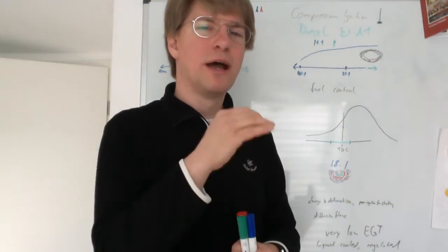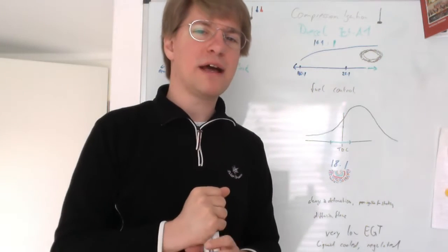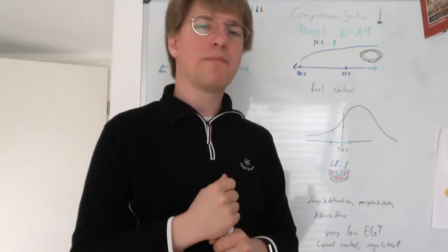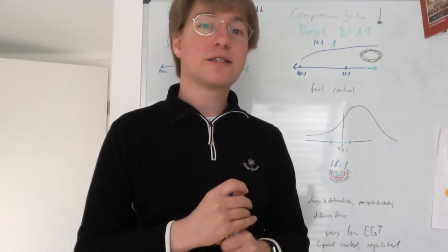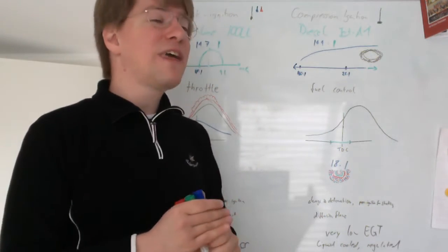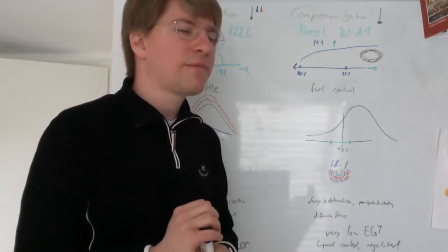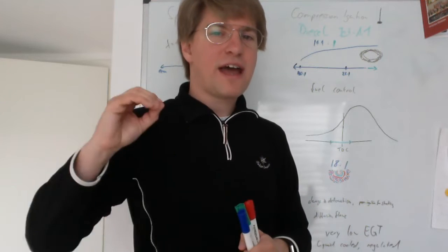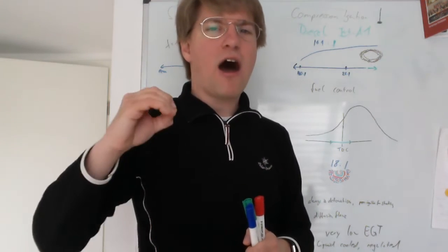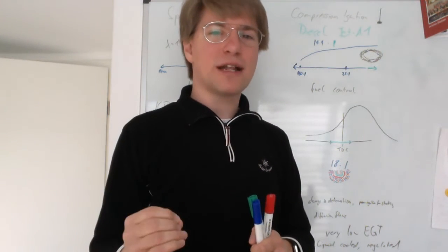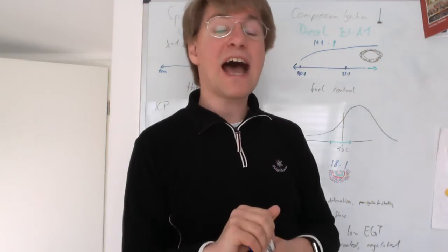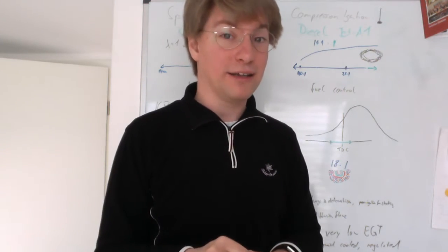Detonation happens when part of the fuel-air mixture ignites by pressure alone. So you can think of a diesel engine as an engine that constantly, always, and exclusively runs in heavy detonation. And that is why they sound so ugly.